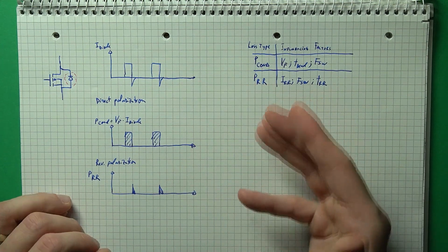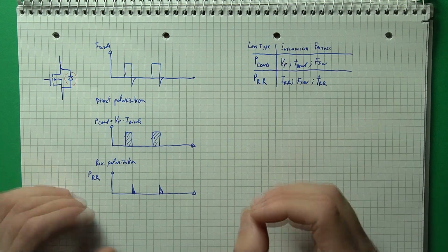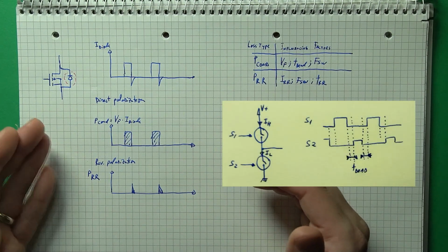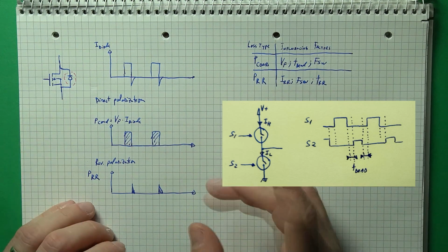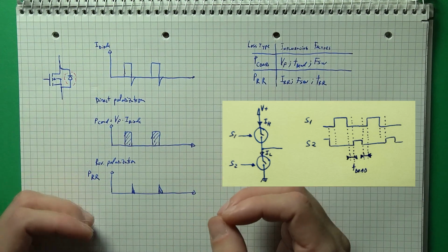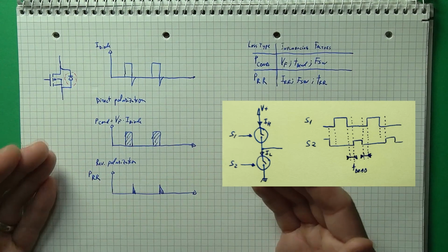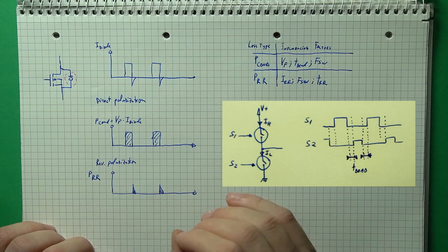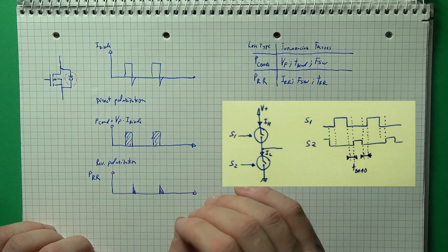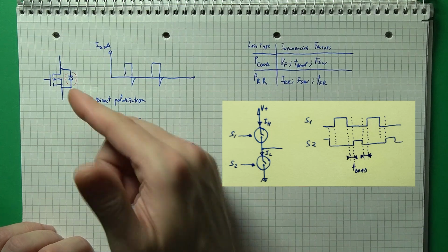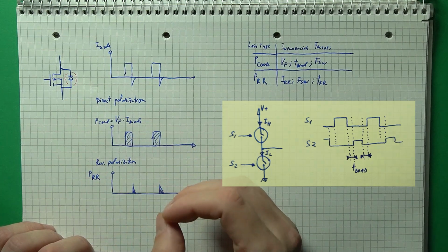In applications implemented with half-bridge drivers like synchronous buck converters, the two transistors are driven in opposition. One is on when the other isn't. However, because the transitions are not instantaneous, and you do not want to run the risk of having both transistors running at the same time, in practice a so-called dead time is implemented, when none of the transistors is driven. This is when the body diode ends up conducting.